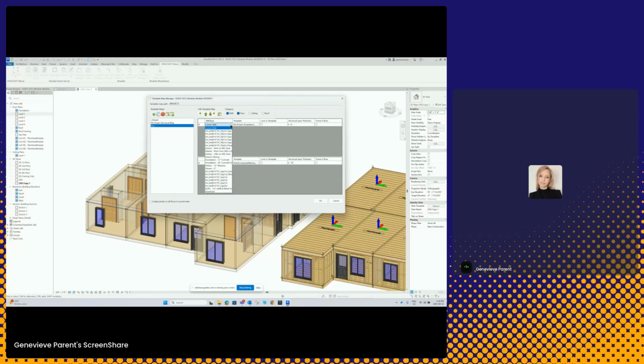At that point, you're going to know your way around this. You simply select which wall you need and which template that you want to associate it with. Now, in this case, I only really set up one floor. So very, very important. Once you want to keep adding these templates for your walls, once I hit here, I'm only going to be clicking on the walls. And then at that point, we can keep adding walls and start setting up our template map.